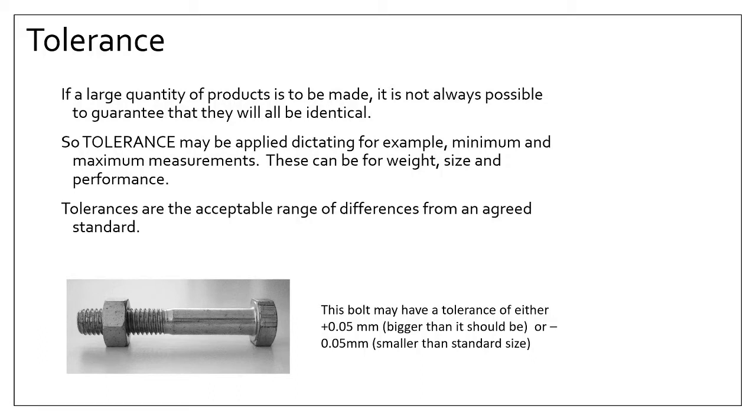So, tolerance. While you are checking things, when you're doing measurements as the process is going on, there's something called tolerance. Things might not always be exactly the right measurement that they need to be, so there's a tolerance either way, written as plus or minus. Take the laser cutter, for example: if you buy 3mm MDF to laser cut, it might not always be exactly 3mm thick. It might be 2.98 mil thick, or 3.02 mil thick. There'll be a tolerance in there.